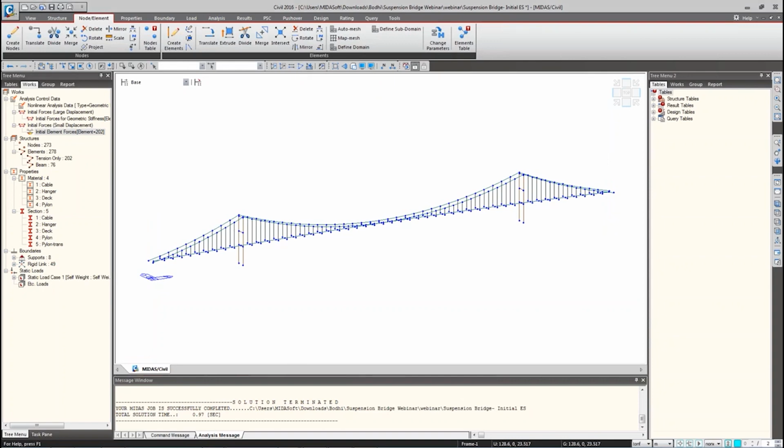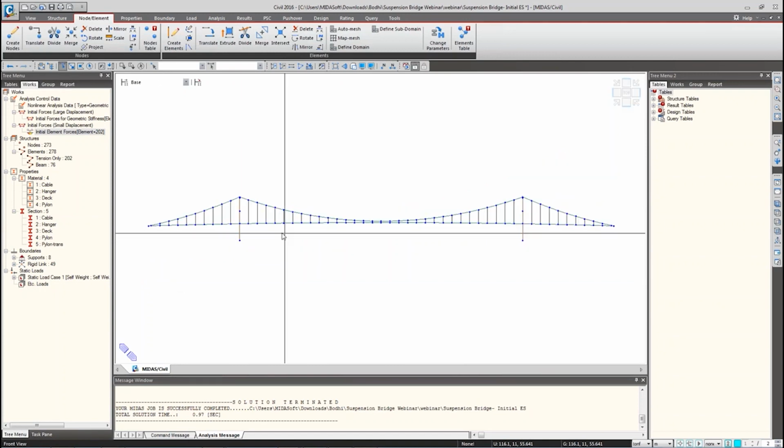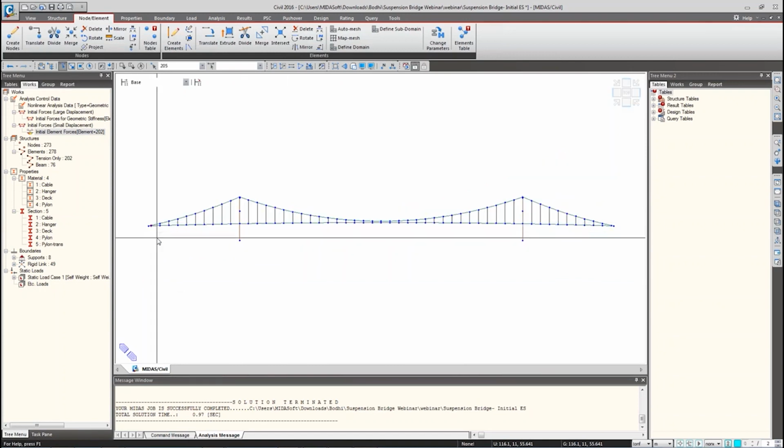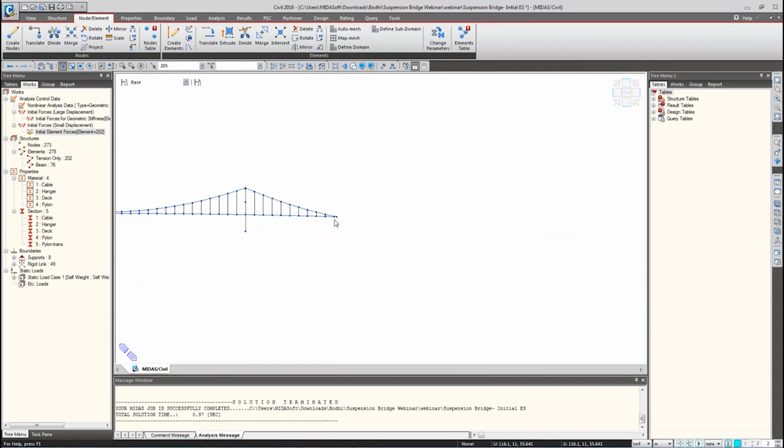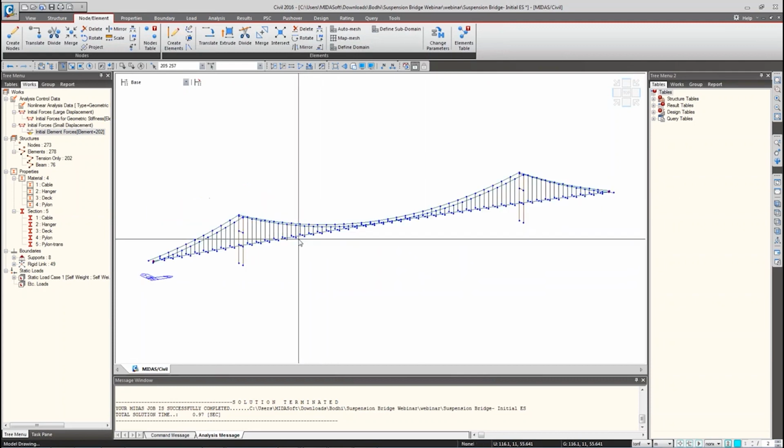Okay. Further modifications that are needed are for the boundary conditions. So I want a deck boundary condition too. I have not given any deck boundary condition right now. So I can go and select the deck end nodes. So go to the front view, select this node and end nodes. These are the deck end nodes that are there.